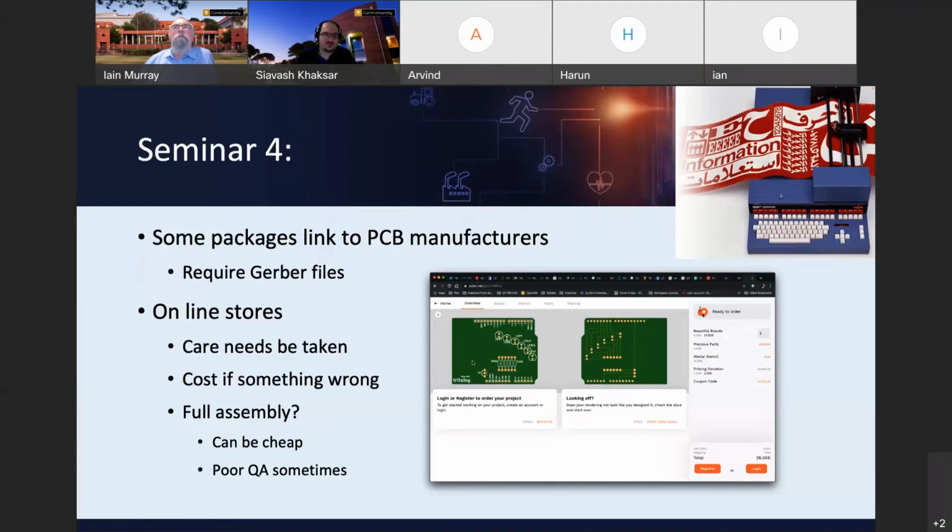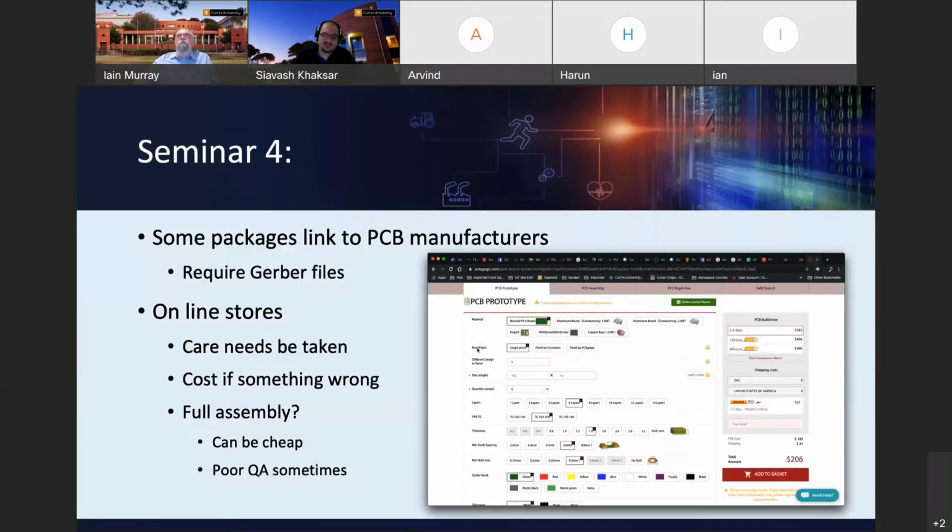But before we had the component shortage, our standard answer would be, well, because it's so cheap, you could just always order your PCBs populated, which means they machine solder all of the surface mount and the regular components in there. But because of the current chip shortage, one of the things that we've had to do at Keratin is sometimes pay for an expensive development board so we can grab an expensive sensor that's just out of stock in a standalone format. So solder out the sensor from the dev kit, or solder out a microcontroller that we need with the specific specs, and then solder that on the prototype. So the soldering skills become pretty handy these days.